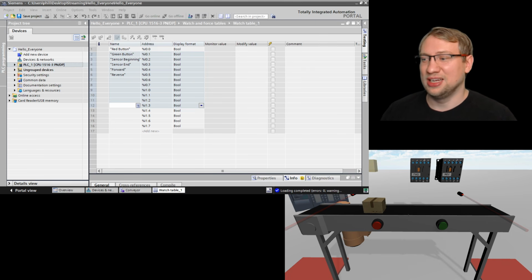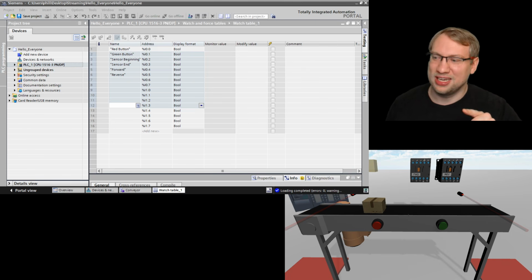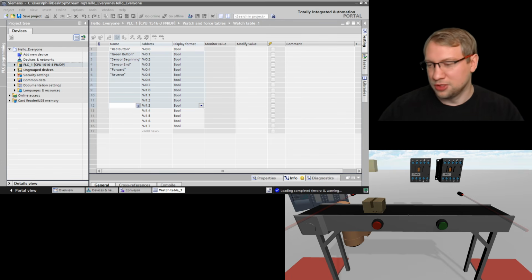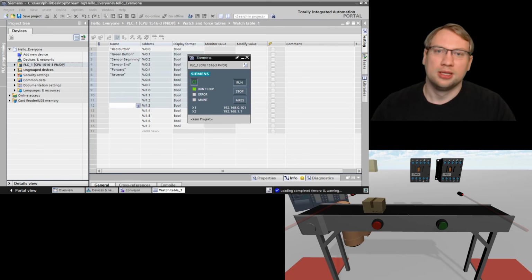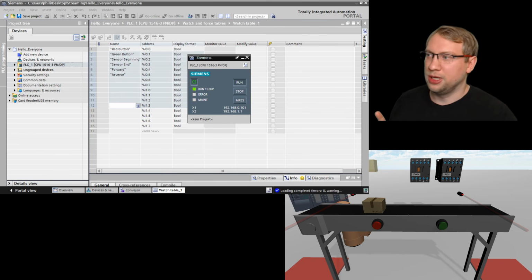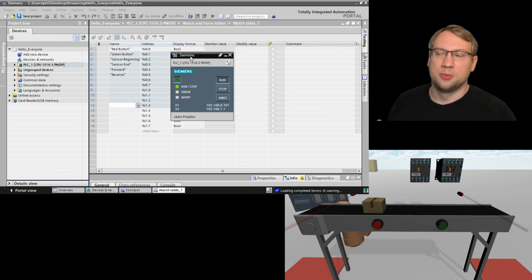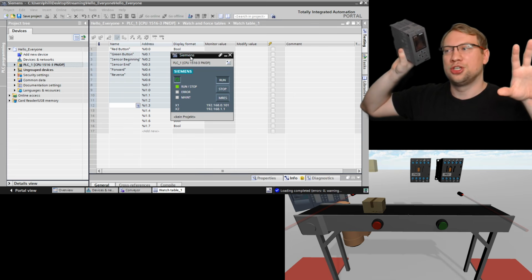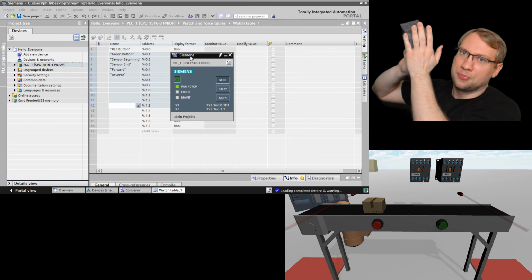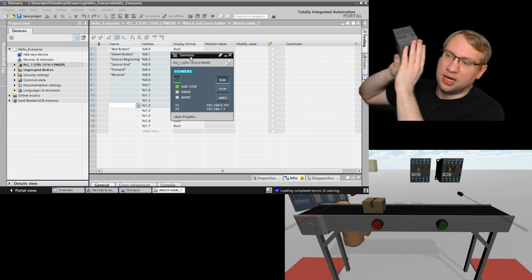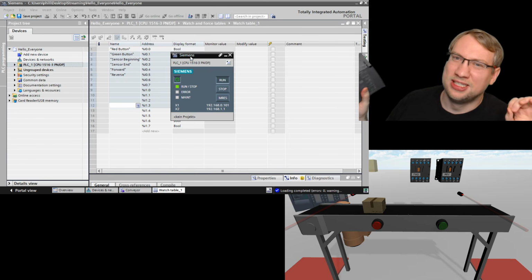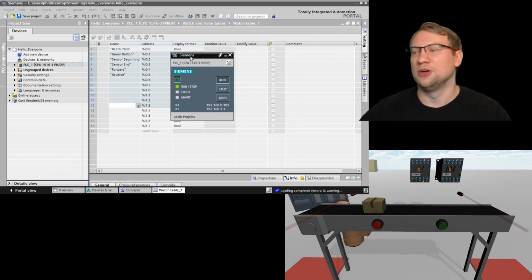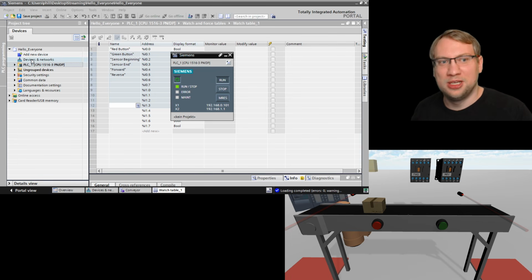Yes, what you said, that didn't show up in my case, was correct. If you turn on the simulation, like I have this window, if this window is open, the simulation here, this little one, I cannot communicate to the outside anymore. It's either simulation or real hardware. That's PLCSIM. PLCSIM Advanced can do both. Why do I have two IP addresses? Simple.